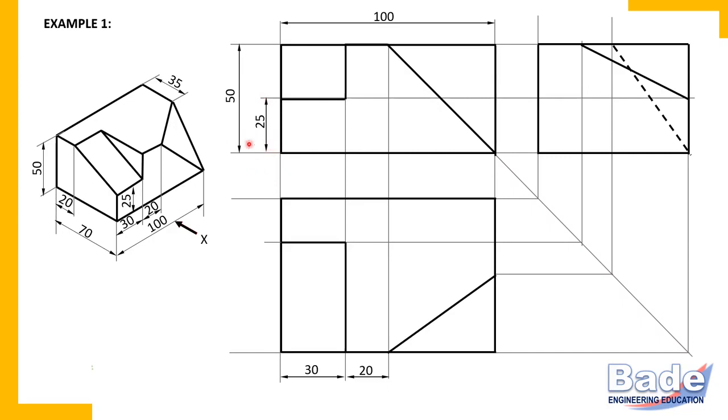And distance between two parallel dimension lines also must be sufficient, at least 8 millimeters you can say. Okay. Now 25 height and 50 height. Any other dimensions parallel to height? No. Now let's focus on dimensions parallel to width. So overall width 70, but before that, smaller dimension parallel to width, that is 20. There is dimension here 35 also, and then largest dimension 70, that is overall width of the object. Okay, so 20 millimeter. In the top view width is, in the side view also width is. So in the top view will prefer.